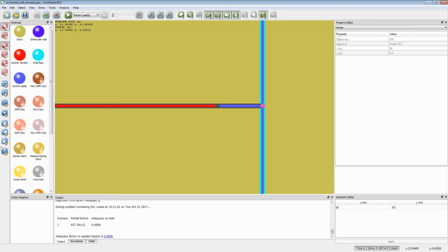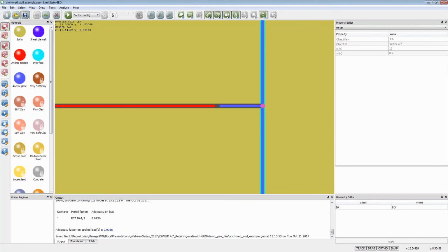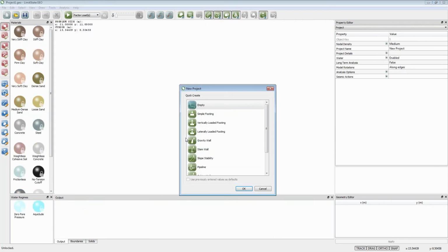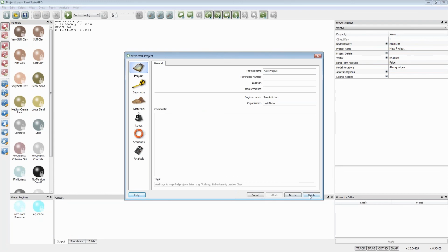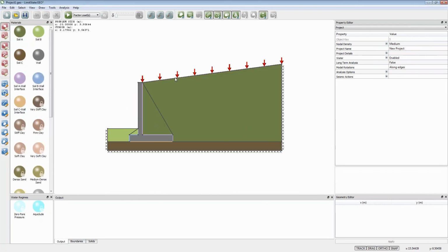Another question, virtual back. Let me just open up that. So this is a wizard that's drawn a cantilever stem wall. Now, in classic analysis on that, one might have a virtual back on the wall in order to work out pressure. The software doesn't put in virtual backs. It doesn't know what it's modeling. It's just modeling a set of materials and certain geometries.